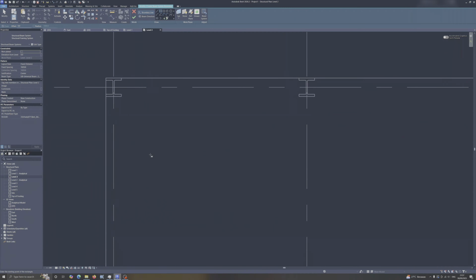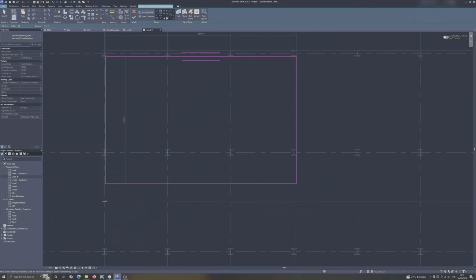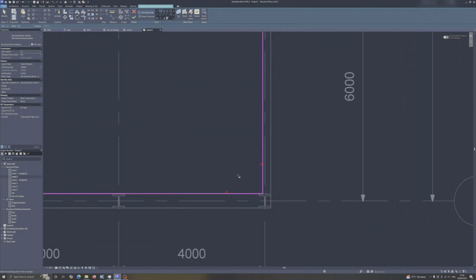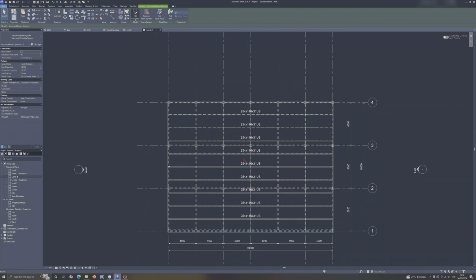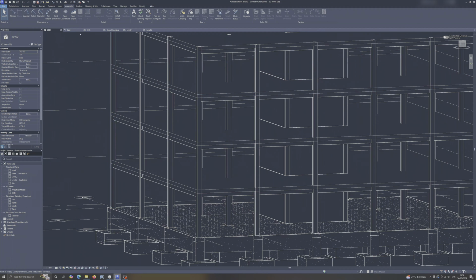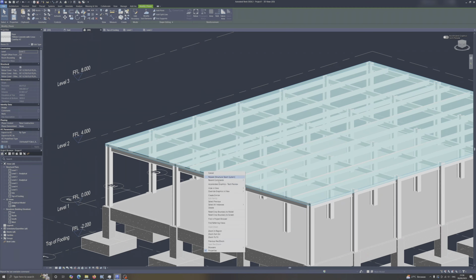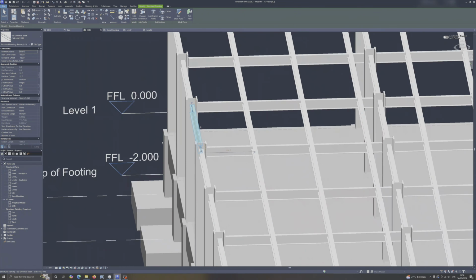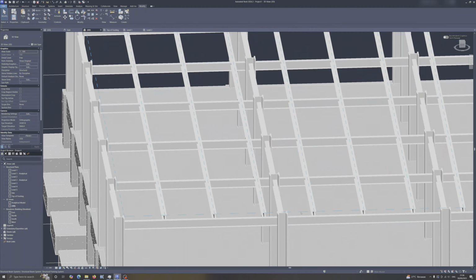Click on Sketch, and you can draw it from the inside span over here, inside span over here, and click on Finish Edit Mode, and that should draw us secondary beams like so. So let's hide the slab and let's try to fix what we have over here.